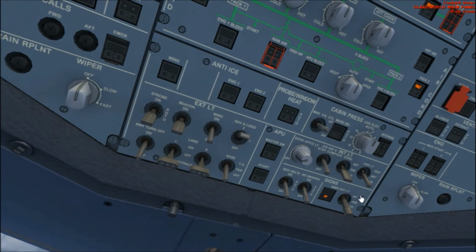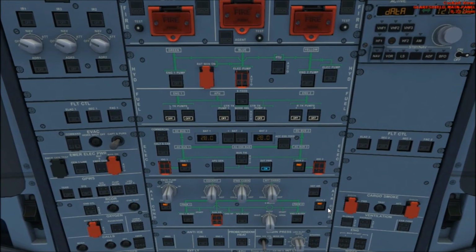Emergency lights. Now, emergency lights, we just left click that once to arm it. Set. No smoking, no signs, smoking, we just click that two times. Set on. Anti-ice, are off. Cockpit window heat, is off. Air conditioning, checked. Ventilation panel, checked. Electric panel, checked.